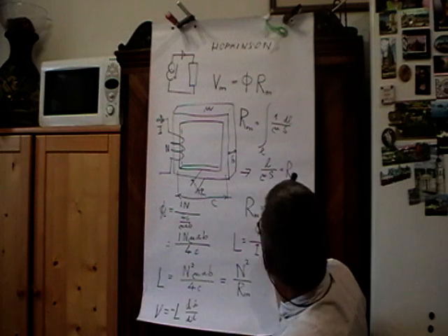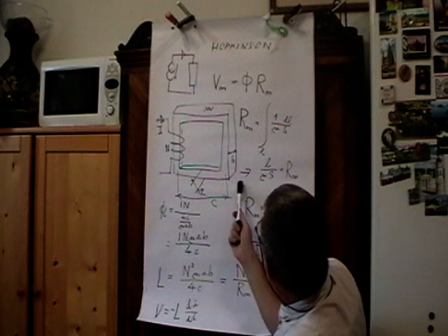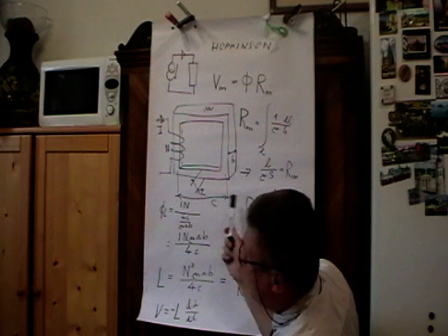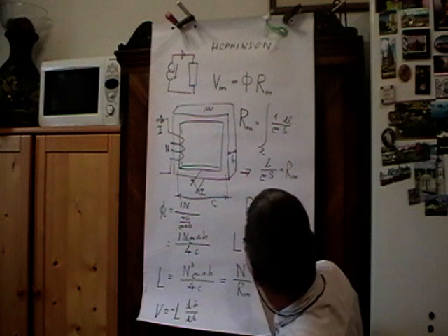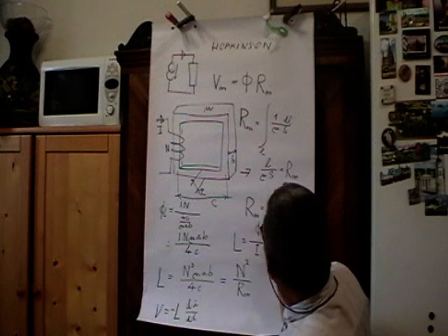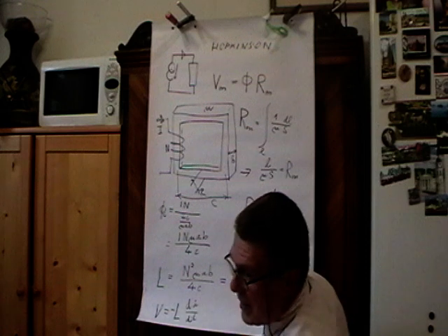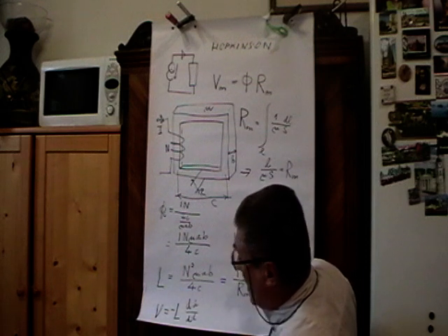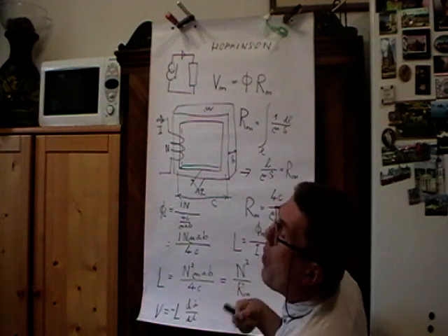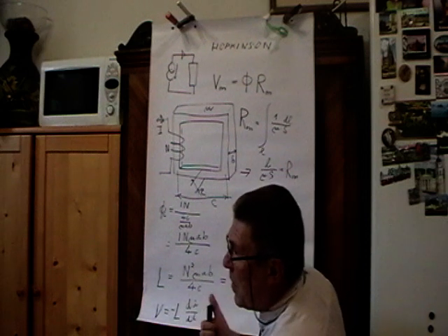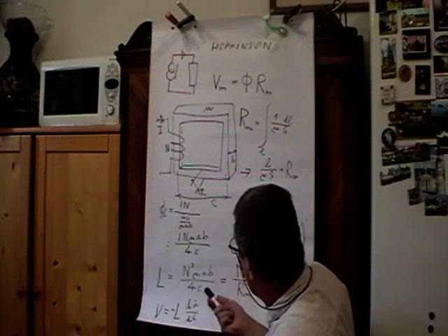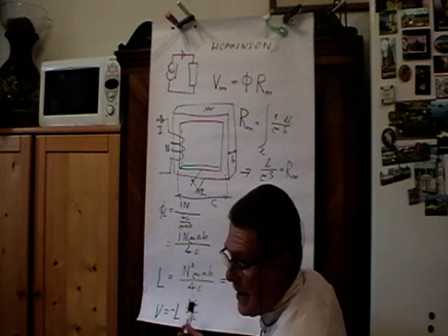Then we used a simple case to calculate reluctance, which is defined integrally but could in many cases be simplified to a simple fraction. Then we found the flux in the core. We multiplied it by the number of turns to get the flux through the inductor, and then we established the inductance.